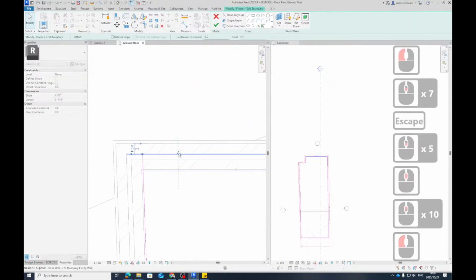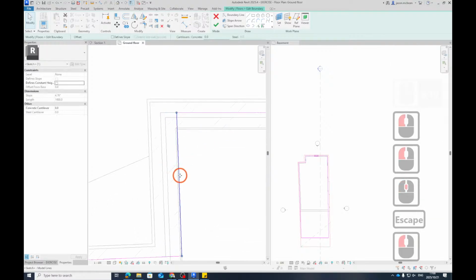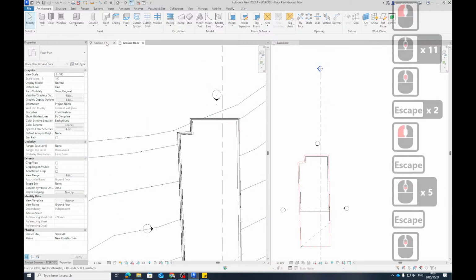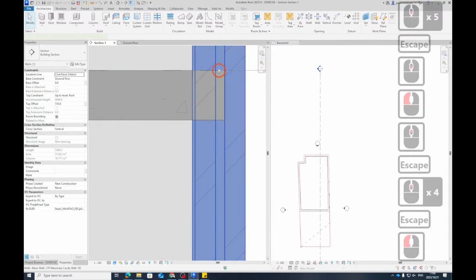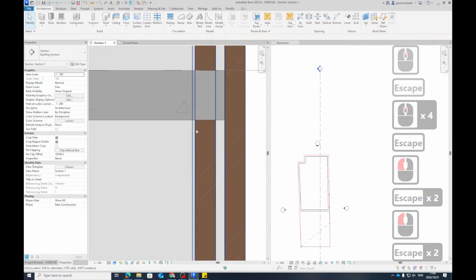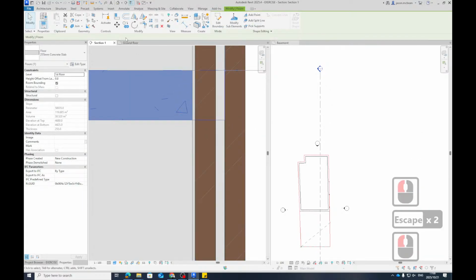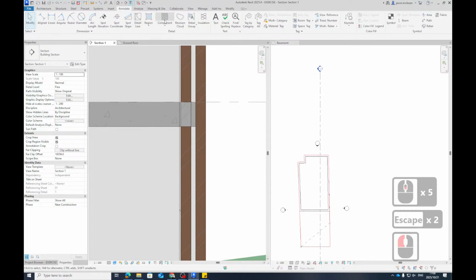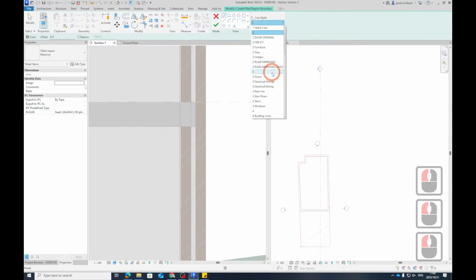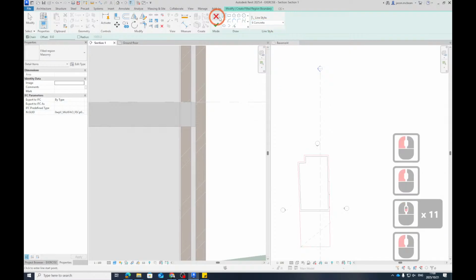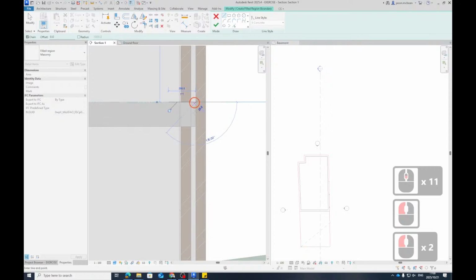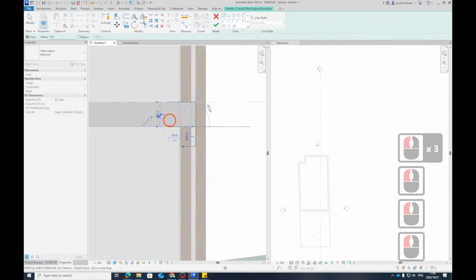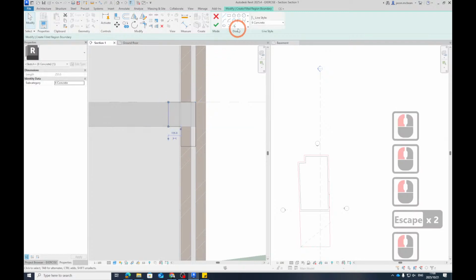You can drag and snap these now. Revit will always try and snap things to each other. It'll try and create a relationship with each other. Okay, just like that. Bang. If I go back to my section, this is exactly how it's going to work. Now you can go and spend a whole lot of time putting a beam edge, but there's actually a tool in Revit that will help you change the way this looks. But technically, I go to annotate. This is very easy. I go to region, I go to concrete, and I quickly draft now. This bit of line work is an invisible line.